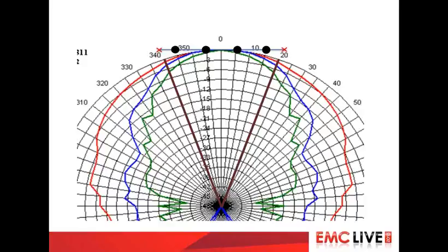Then if we look at the blue one, and do the same thing, go right, go right, go right. Wait until it intersects with our brown line there, the limit of the zone of interest. I'm going to say that's 2 dB, given that's a 3 dB box. So we now have, at 1 gigahertz, a beamwidth loss of 1 dB. And at 9 gigahertz, maybe a little under 2, but I'm going to call it 2, because our system requires 10 gigahertz.